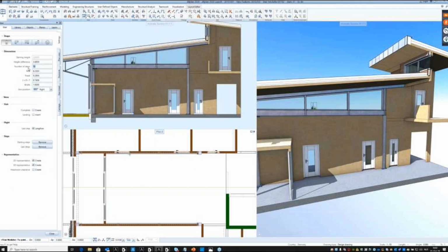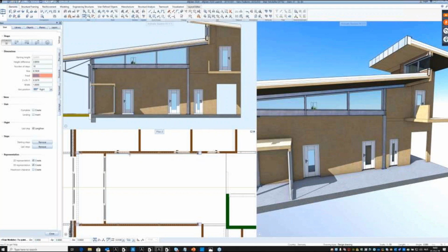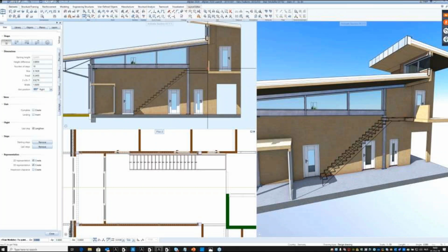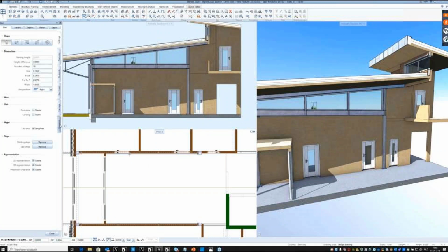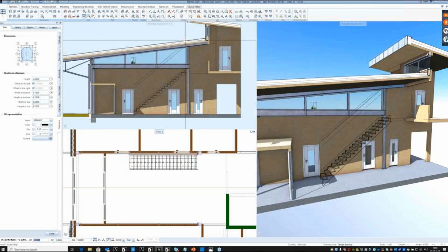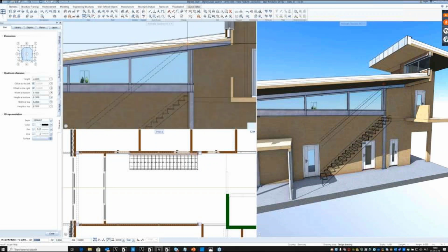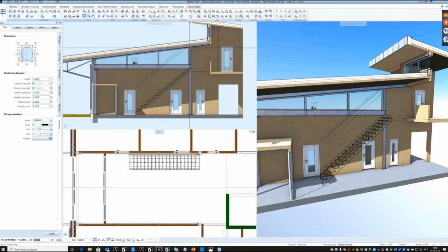But you see, we need to make some landing on top of it. We cannot just respect a certain height of the stairs. It's quite difficult to get there without getting into conflicts with other items. So we can calibrate now the height of the thread, the width of the threads, and establish what is the best solution to get to that stair. But you see, no real clicks are done, so we don't model the stair and redo it. We just preview it.